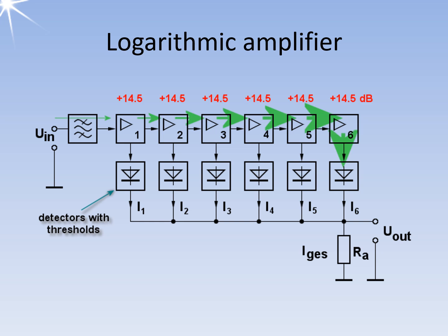All amplifier stages are designed to amplify small echo signals without reaching saturation. Unlike conventional intermediate frequency amplifiers, the linear amplification range does not terminate at a specific saturation point. As a result, when a larger signal is present, it does not saturate the logarithmic amplifier. Instead, it simply reduces the amplification of a smaller signal that is applied simultaneously.